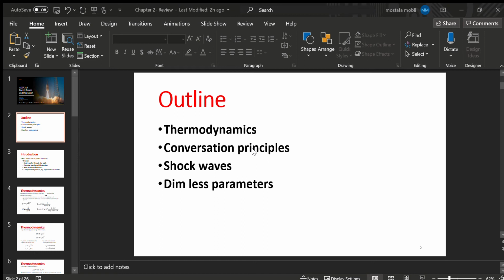We can also define the specific enthalpy and energy of the system using these two formulas. Essentially, we are saying that the enthalpy and energy of the system is a function of heat capacity at constant pressure and constant volume, and the changes in temperature. The heat capacity at constant pressure and constant volume itself is assumed to be a function of temperature. If they are a function of temperature, we call that gas a thermally perfect gas. Okay, and there are a range of temperatures in which we can assume Cp and Cv are constant, don't change with temperature essentially.